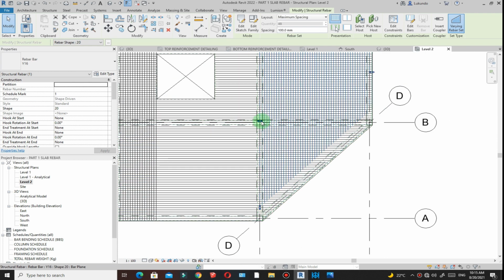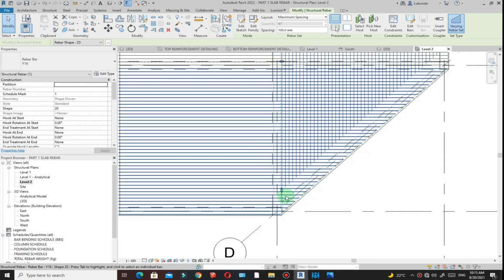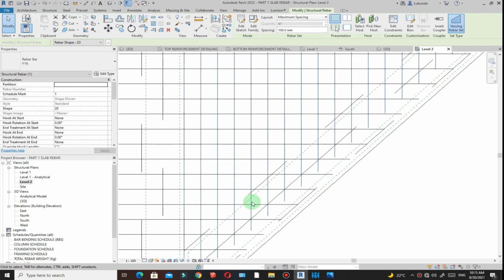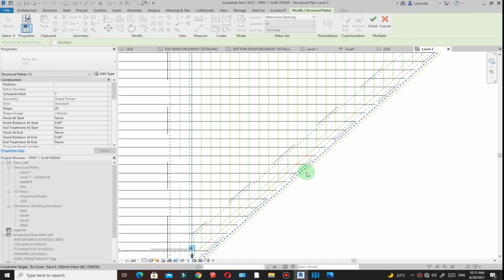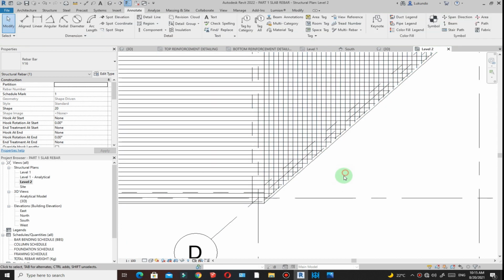So if you see that, it means that you need to drag it outside so that it's within that varying rebar end, or the slab edge. Then drag it down like that. Then I'm going to use the edit constraints, pick that edge and pick the cover, then click there and put a 0, then click outside and finish to lock it right there.